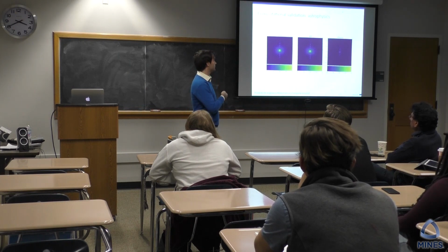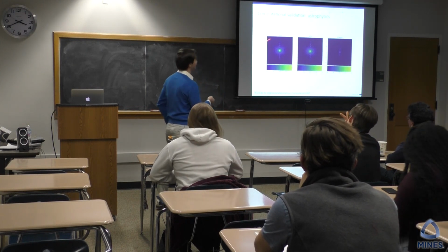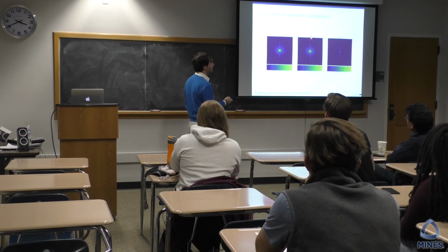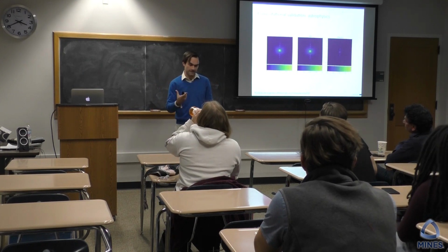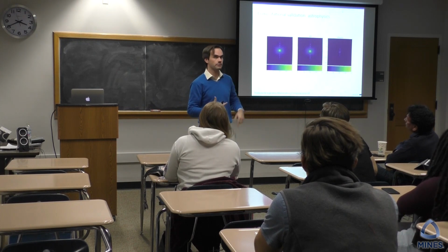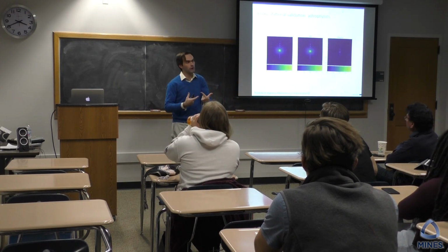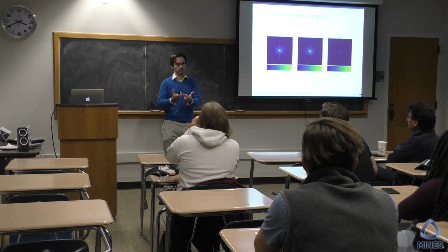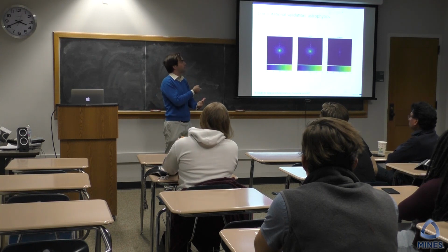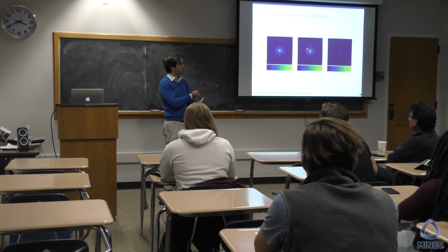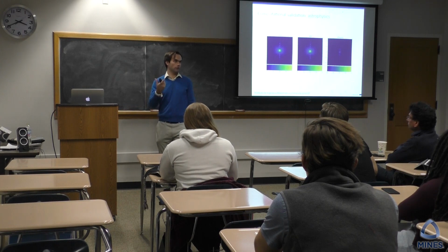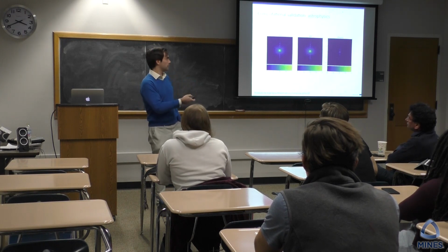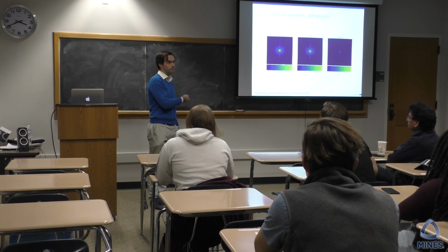Now one reason: for GRASP you need to pay $10,000 a year. BEM-PP is open source and free to use. The mathematical or more scientific reason: remember that BEM is a full wave solver. GRASP is based on physical optics, so you do have more assumptions in your model. So GRASP has more assumptions in its model than BEM, so I do expect that BEM is better performing in this test case than GRASP.